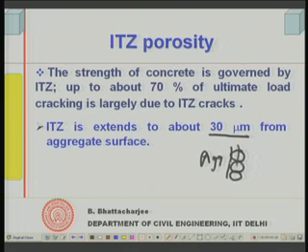So, in this zone the packing cannot be as good as the bulk paste where there are all cements. So, this is the zone where there are weaknesses, right. It could be slightly more than half the average cement size actually.